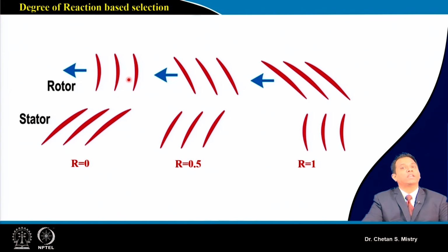Now you can ask what angles we are deciding. We are looking for the blade passage to be designed. We need to use the aerofoil, and that's where what we learned is helping us. So you can see this is a constant area passage. Here, if you look at it, my entry area is lower and my exit area is larger.